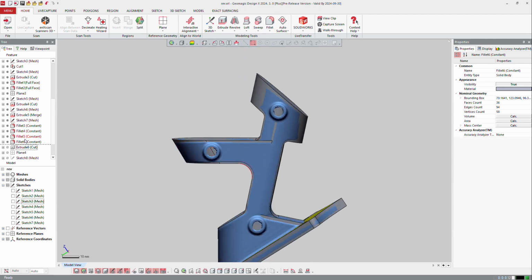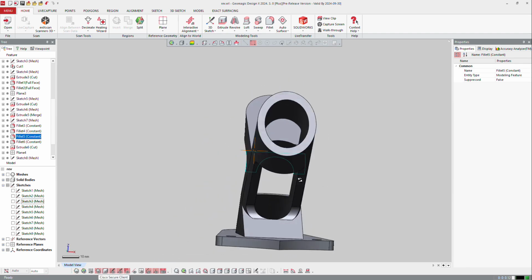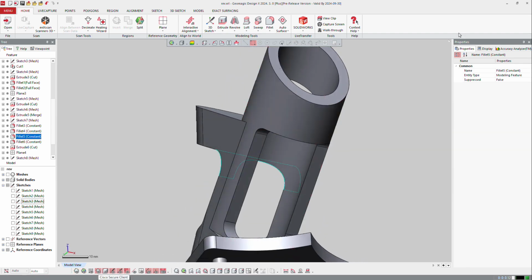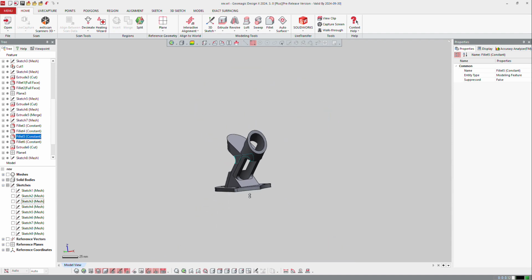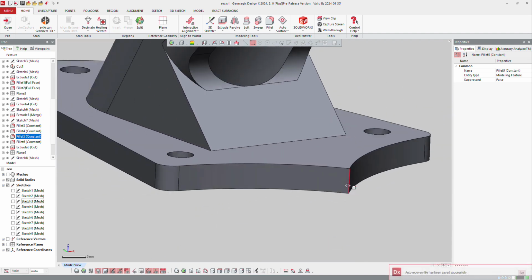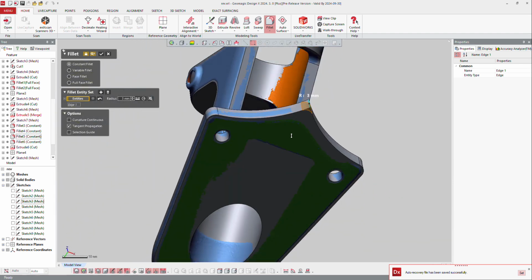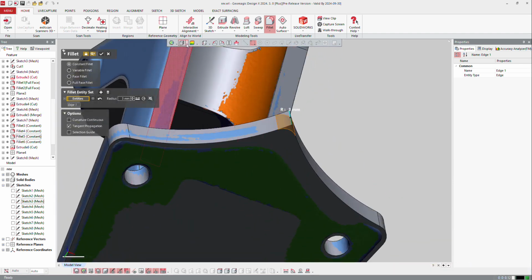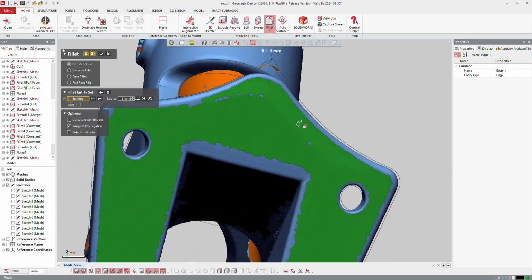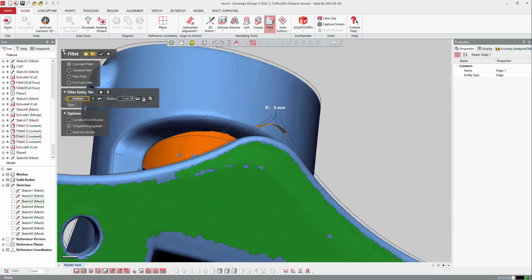All right, so now I can go back to the end. So right mouse click, roll to end, and the software reproduces everything here on the part. Now, as at the beginning, I said I want to make that edge at the end, right mouse click here, fillet. I can always display that shape and ask the software to display my CAD in transparency here, and I can see now the fillet. I can estimate the fillet. The software will try to find a good value, so 7.6, maybe a little bit more, 7.8 on 8 millimeters.